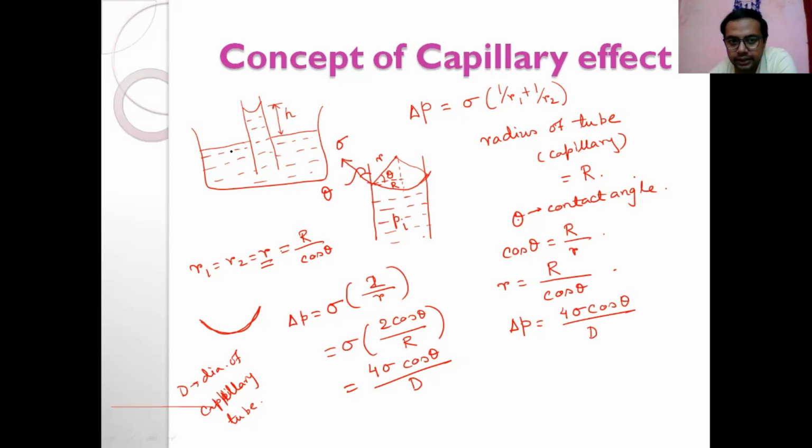Here, lower pressure, that's why fluid is coming inside, and there is a rise. So what is the pressure difference? This pressure difference is causing this height, capillary height. Needless to say, it is H, rho of the liquid, density of the liquid into gravitation, H rho G.